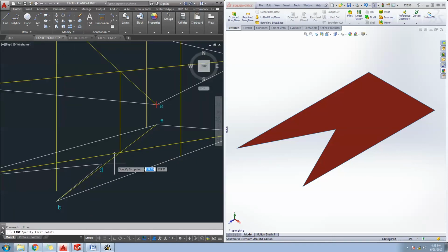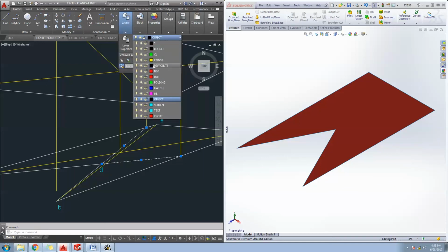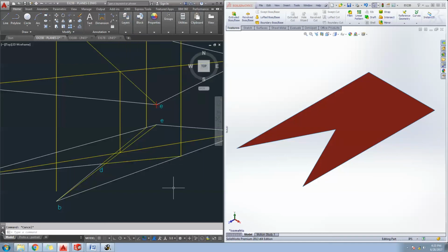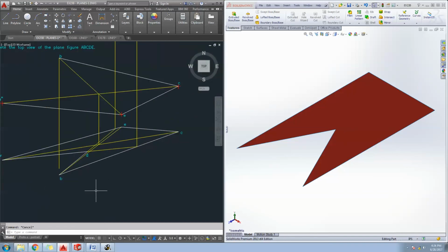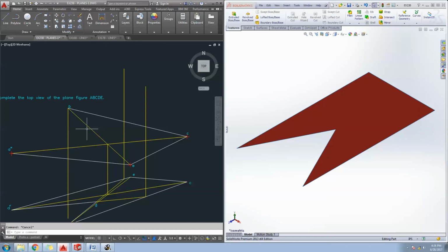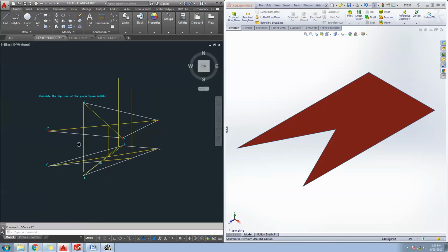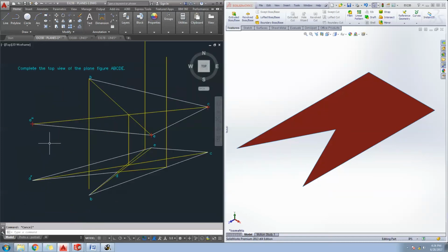We'll go back into the construction layer and we will connect, make that geometry be construction geometry. Now it's getting kind of messy, and that's okay. There's going to be a lot of lines. There's just always going to be. So don't panic about that too much. Now, this is the intersection between A, D, and a point on line BC. So that's that point right there.